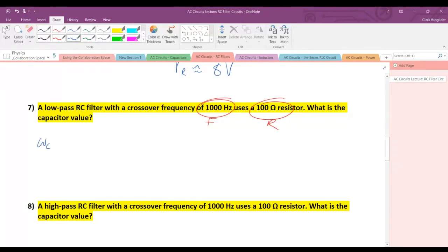So we can pull out this equation. I'm not going to be developing equations. That's textbook stuff. I'm just going to go to them and grab the thing that we need. Crossover frequency would be omega sub c, as written here, and one of its independent variables would need to be the crossover frequency, and it ends up being the case that this is 1 over RC, which is kind of nice, right?